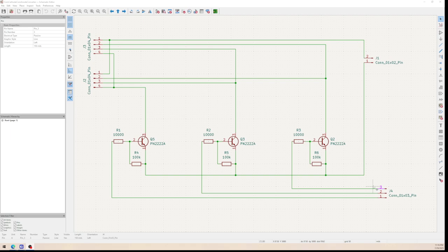Down here you have your red, green, blue signals that each provide a voltage to your transistors that allows it to complete the ground circuit. So if you have a blue voltage, that is going to supply this transistor, allow this ground to open, and allow the LEDs here to get power and send ground back to the connector.